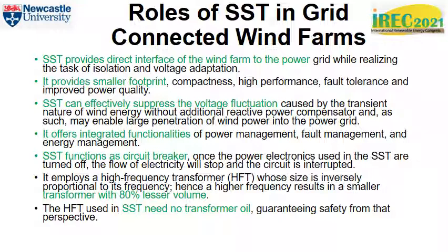Solid-state transformer functions as circuit breaker, in which case the power electronics used in the SST are turned off. Once such power electronic components are turned off, the flow of electricity will stop and the circuit is interrupted. As such, SST behaves as circuit breaker in that case.